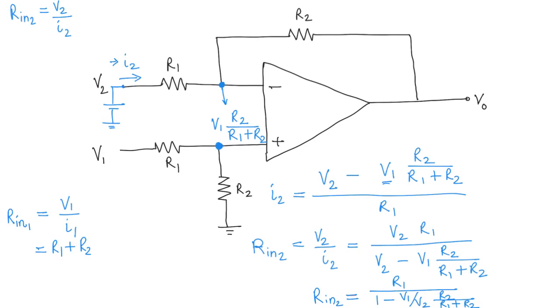When we are recording an electrocardiogram, we put electrodes on the body, and these electrodes are connected to the differential amplifier because we want to take the difference between two electrodes that we have put on the body. But because of these input resistances, they start to load your electrodes and your signal that is coming, and distort your ECG. Now we need to do something so that we can use these circuits without distortions. But that's a topic for the next video.